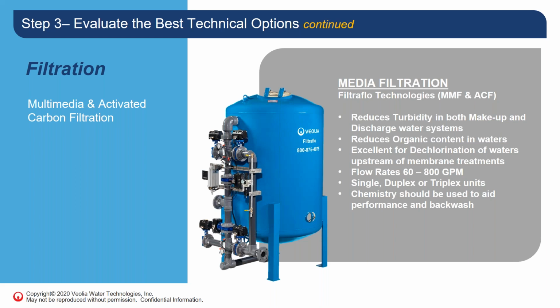Many processes in your plant might not allow a positive chlorine residual because of process requirements, or upstream of a membrane system that does not allow chlorine for long-term membrane life. And similarly, activated carbon can be used to absorb and remove organics from a water stream, where those may be harmful or impact water quality and utilization downstream. So 3 different types of filtration.